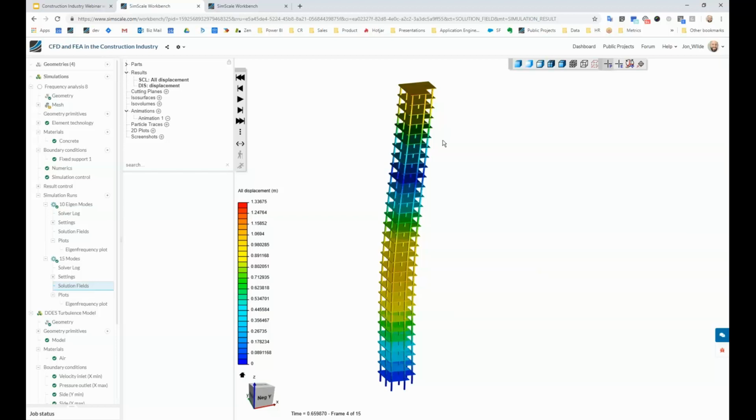And I think you're asking about a series of buildings. We're actually just about to publish a pedestrian comfort study on an AIJ, which is a Japanese city basically, and I suggest you keep an eye out. Once that's published, it'll give you an idea of the huge scale that we can work on with the lattice Boltzmann model. And again, if you had any of those buildings open, the flow would simply pass through them, so all of that would happen pretty nicely and accurately. We're doing that to publish a really large-scale validation.